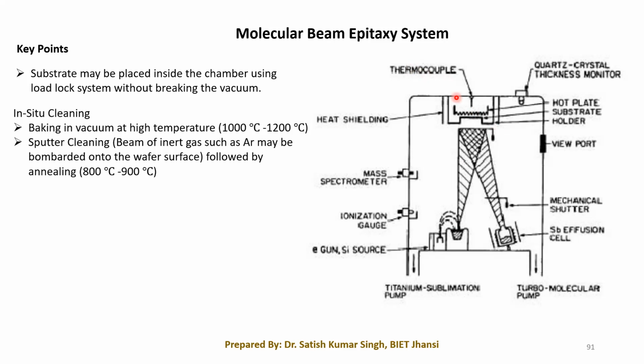Now, because we are evaporating the atoms, the composition of these atoms can also be monitored by a mass spectrometer. We have another device attached to this system, which is our mass spectrometer. This mass spectrometer will keep on measuring the composition of the evaporated atoms, the evaporated gases you can say.